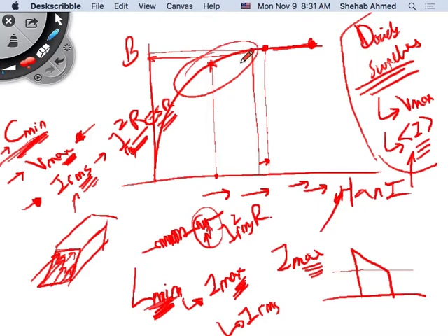So you will select an inductor, you go in and you select the inductor minimum value of inductance. And then you make sure that you're satisfying the I maximum, the maximum flux that you can push into the core. So from that perspective, you actually selected the core. But then you also have to select a wire, right? Selecting a wire will depend on the amount of loss.